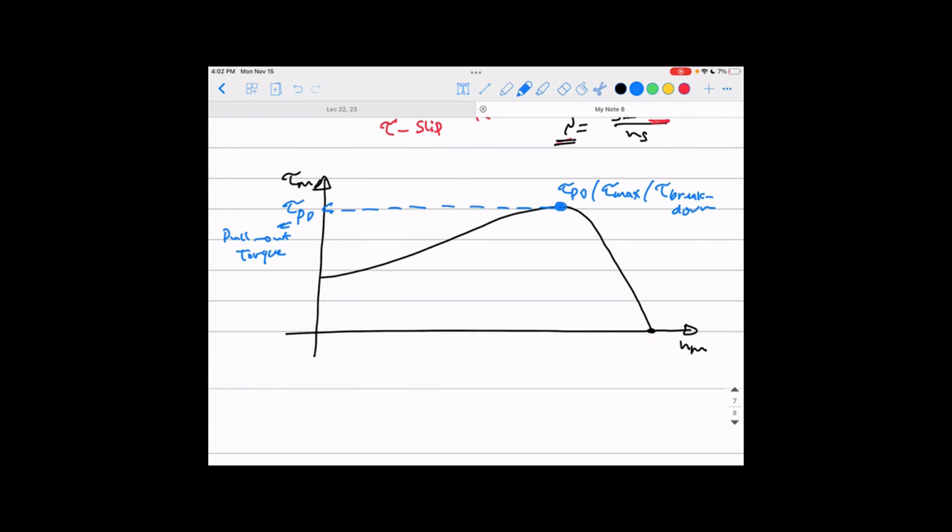That means you have a very heavy torque applied to the machine, which has to develop very high torque. If the torque is higher than this value, the machine will break down. That's why on this torque speed characteristics we have two zones. The right hand side zone, we call the stable zone. The left hand side, we call the unstable zone, or sometimes the breakdown zone.